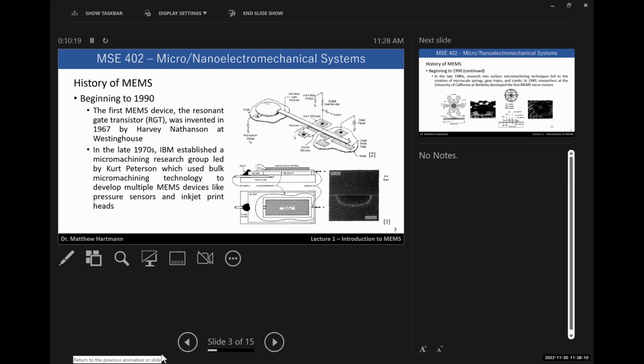When the piezoelectric crystal has an opposite polarity voltage, it shrinks, causing a small amount of vacuum pressure to suck more ink into the cavity, and that cycles over and over again. So you have this membrane deflecting down to push ink out, deflecting up to suck ink in through the reservoir, and then it's spitting out little ink droplets all over the paper.